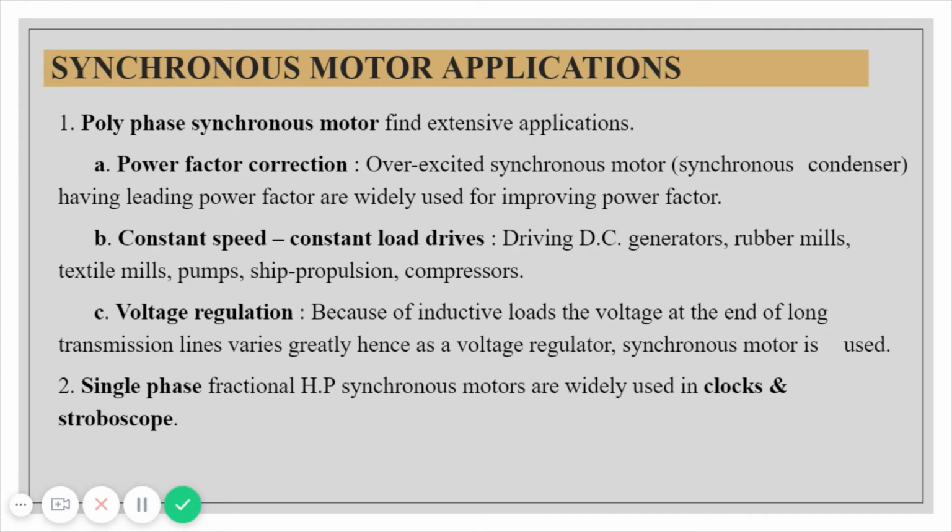The applications of synchronous motor. Synchronous motors have many applications. First, understand the polyphase synchronous motor applications. The first one is power factor correction. An overexcited synchronous motor, or synchronous condenser, has a leading power factor, so it is widely used for improving the power factor.